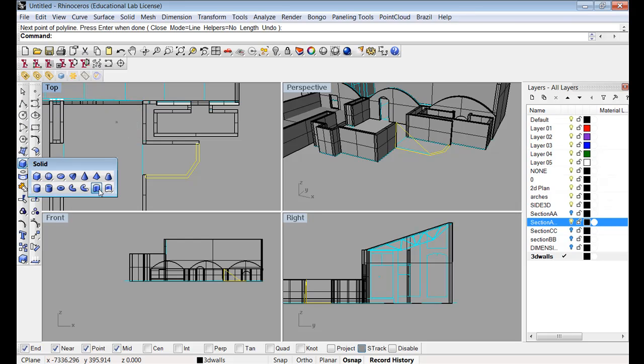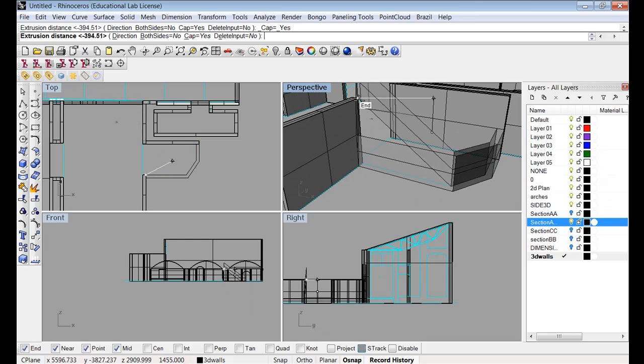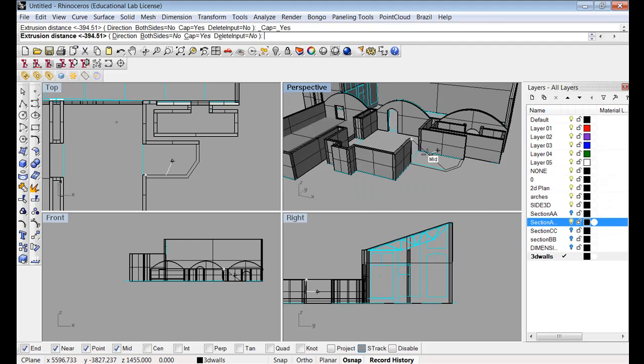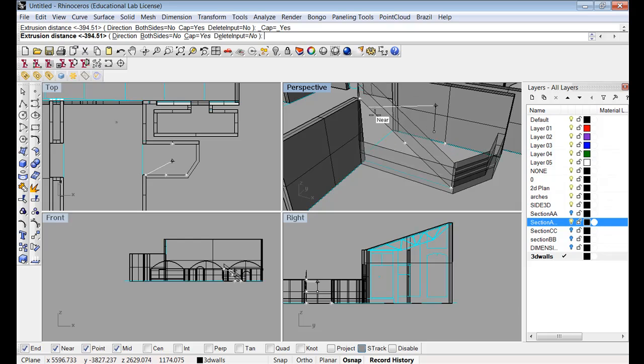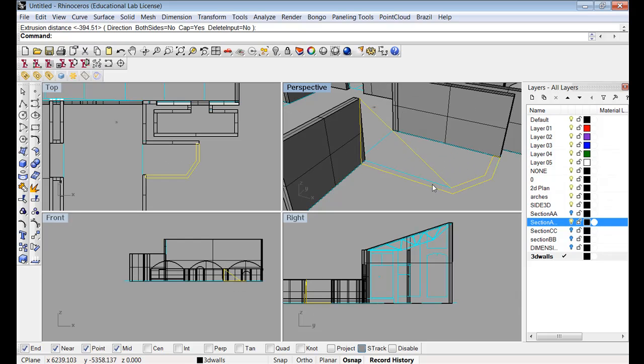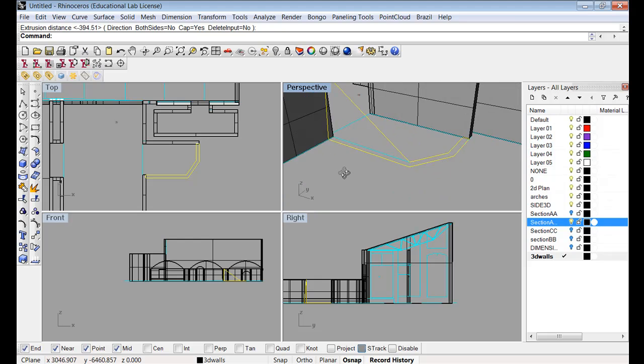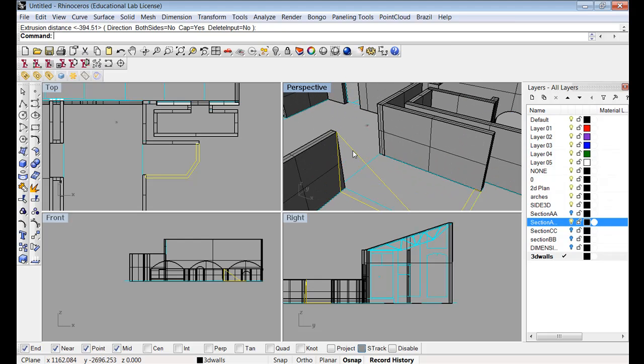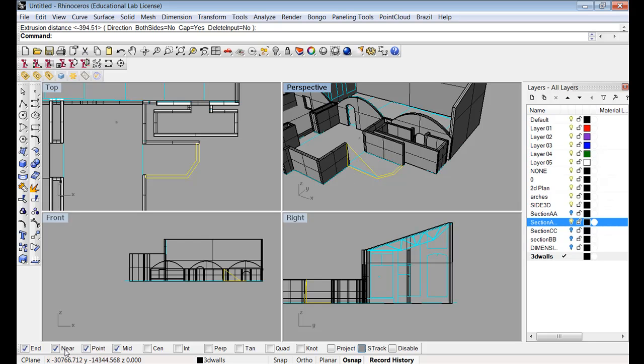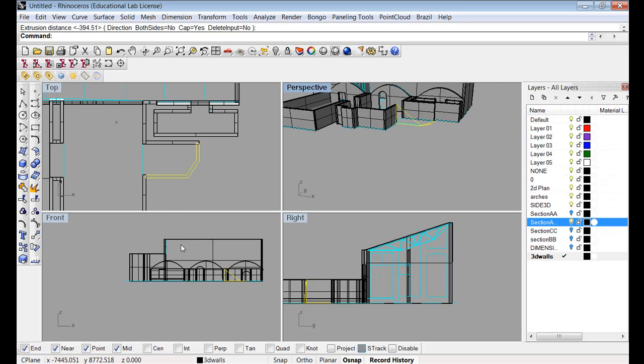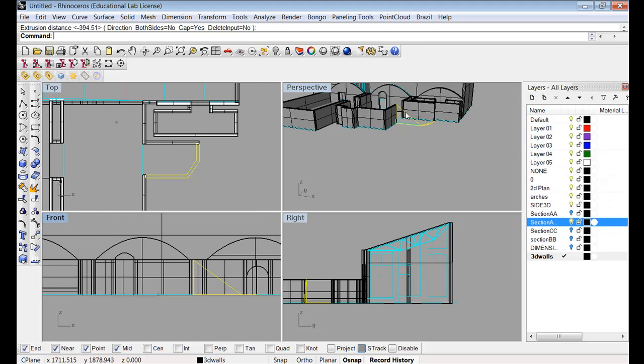And once that's done, I can go to here and I can go, ooh, but there's a problem with that. Notice, can you see what's happened there? That's basically because it's locked onto a point on the 3D object, and that's what you got to be careful of. In order to extrude up a nice flat shape, my actual sketch itself, my drawing needs to be straight, whereas if we look at that one, it's far from it. Although it looks in that view like it is, when we look in this view it's not so.